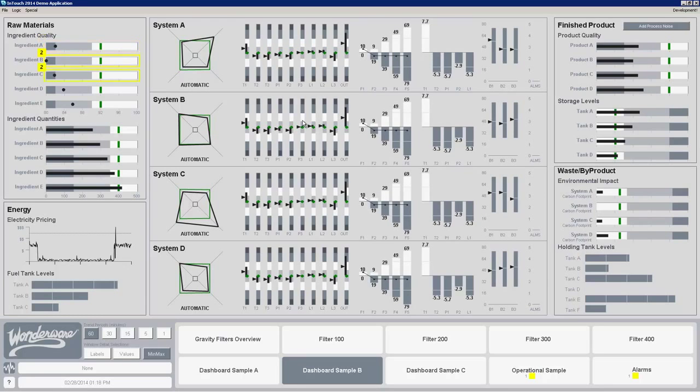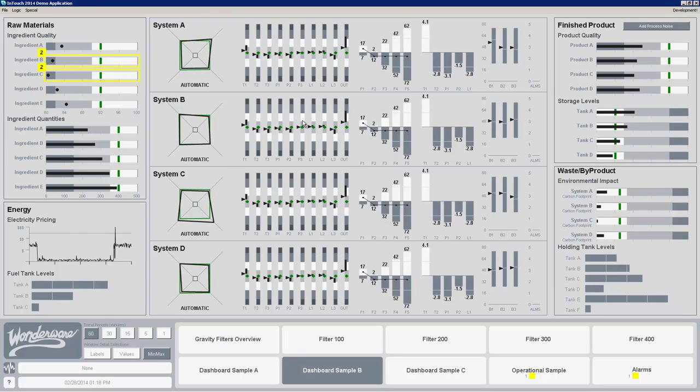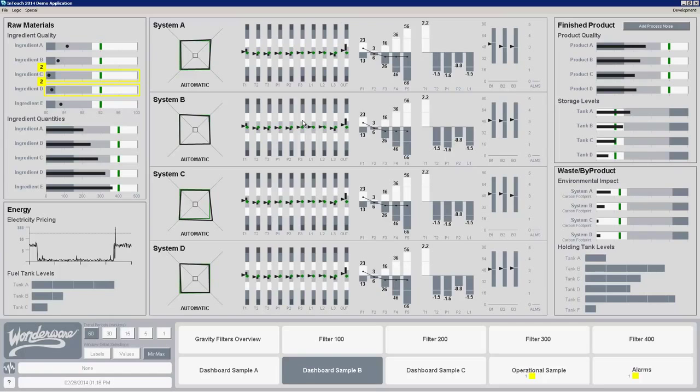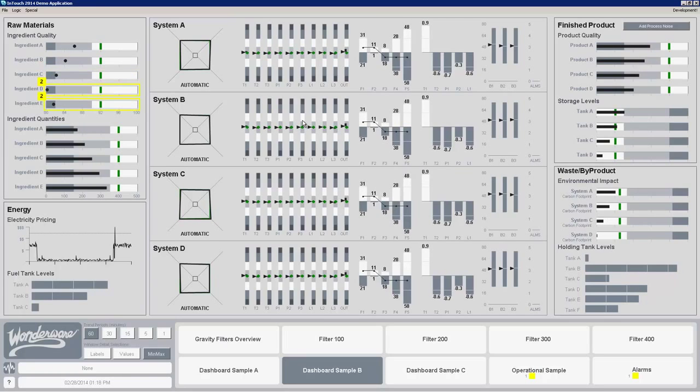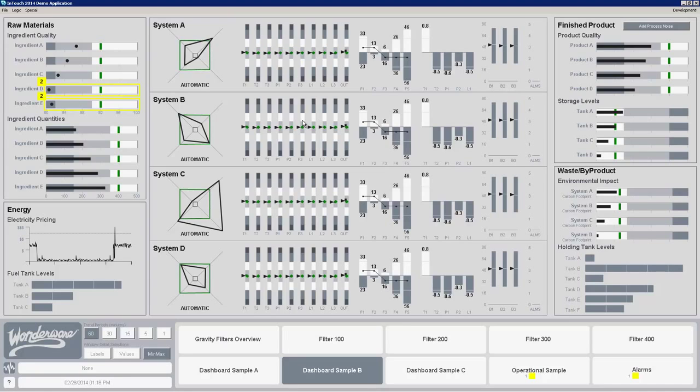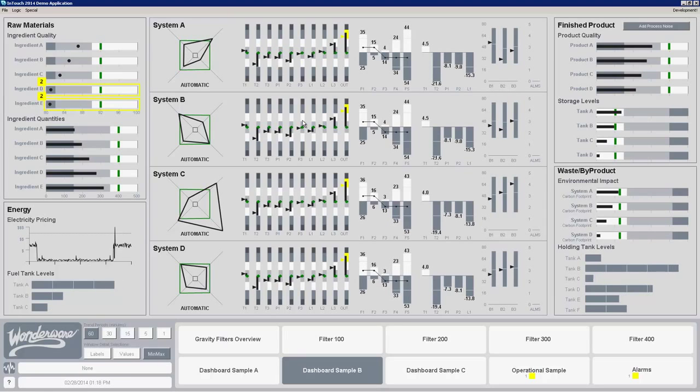But I'm not necessarily orienting this level 1 graphic at action. Really, it's just an awareness. If I had a central control room, or a process that was large enough to justify a central control room, this may be the screen that was up on the wall, the one that maybe was very rarely changed. It's the one that I always wanted to have available. But sometimes your processes may only have one screen, and you may need to have this as just your basic system overview.